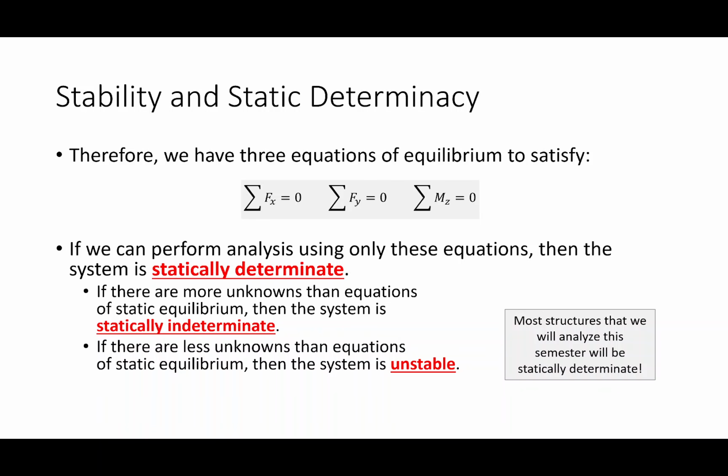Okay, so what I'm saying is that whenever you have a situation where you can analyze the structure using nothing but statics, we have a name for that, and we say that that structure or that system is determinate. That's what a statically determinate system means, that we can solve for everything going on inside that system with just statics, with just equations of equilibrium.